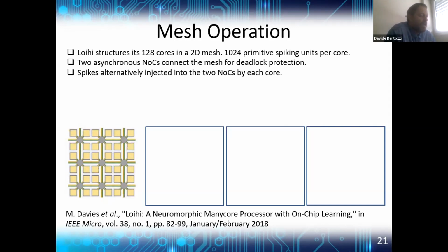For instance, you have memory requests and memory responses, and if you accommodate both of them onto the same network on chip, you may close a cycle through the cores. So you may end up in a deadlock condition, similar to the routing deadlock of the network on chip itself. In order to avoid these blocking conditions, typically you need to associate either a virtual channel or a separate network on chip to each different message class. And this is what is done here.